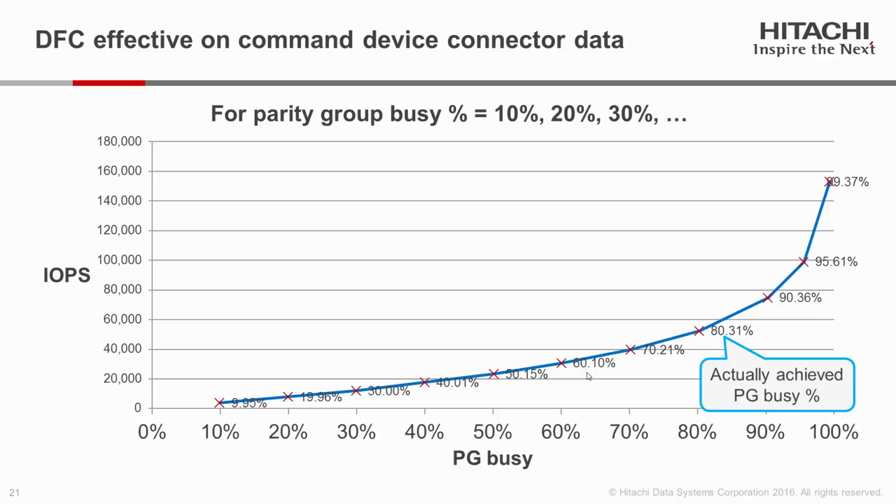And this allows you to directly calibrate modeling tools, for example. And the curve, you can see it tilts up at the end here because these are HDDs, and as the drive percent busy goes up, there's a proportion of reordering of in-queue IOs to reduce the mechanical positioning time, to reduce the rotational latency and the seek time. Then we can fit more IOs in the same amount of time, and therefore the curve tilts up at the end.